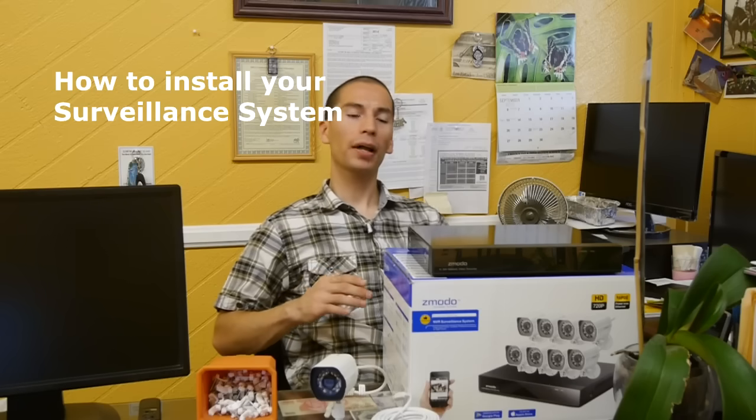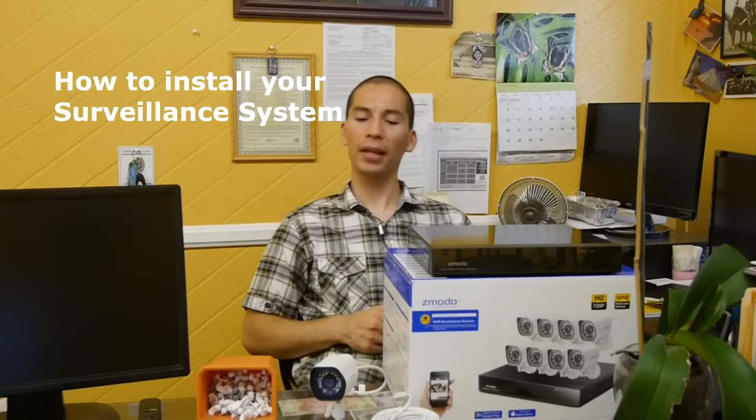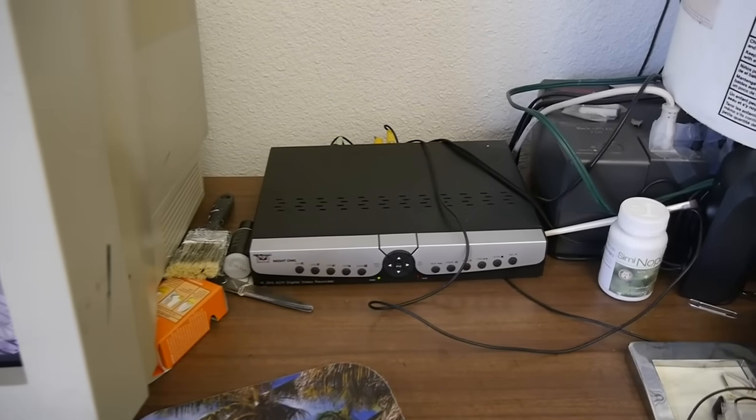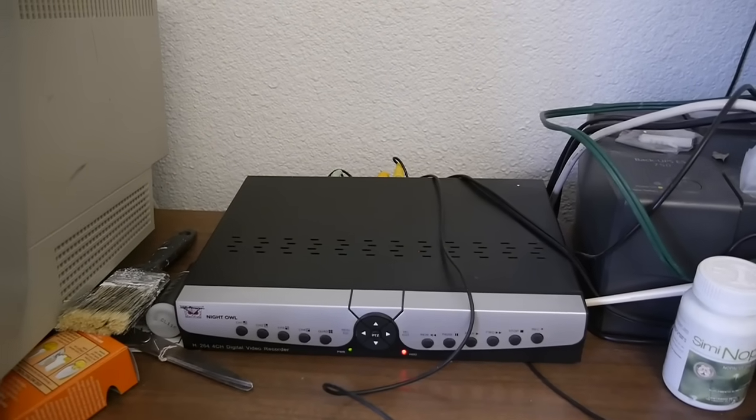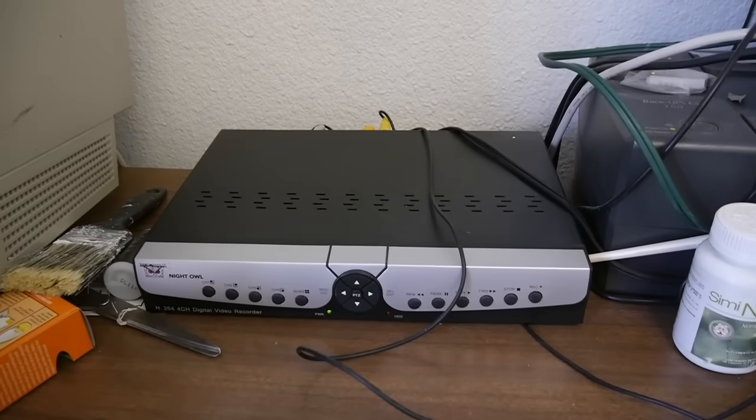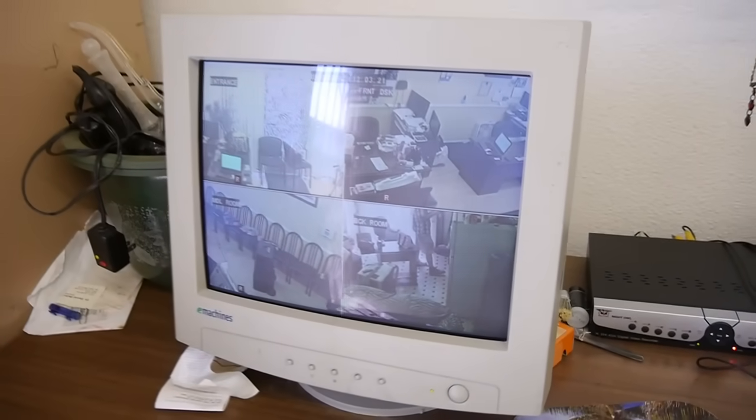In this example, I'm going to install an 8-channel NVR system that includes 8 720p HD IP cameras and an NVR video recorder. Using my own advice, I purchased everything together as a complete kit that includes a set of cameras, cables, and everything, but without a hard drive installed. I'm actually replacing an older 4-channel analog system here at this office that I installed back in 2012 because the business owner now wants more cameras. So I'll be swapping out the hard drive from the previous DVR to this new NVR. And as for the monitor, we're going to use an old school computer monitor that we already had on hand.